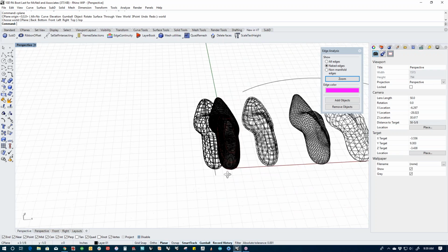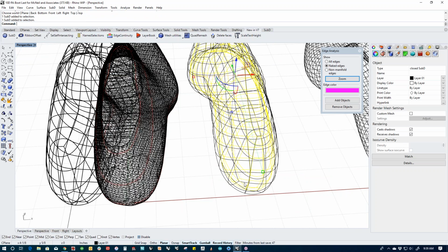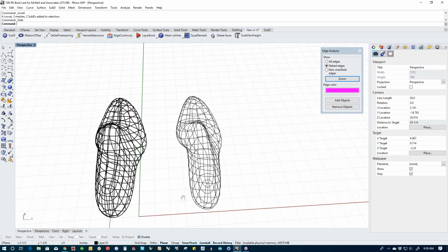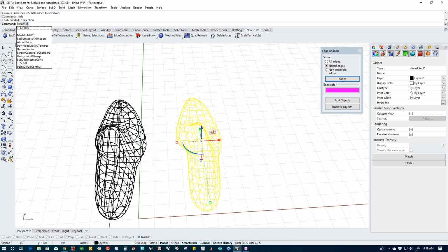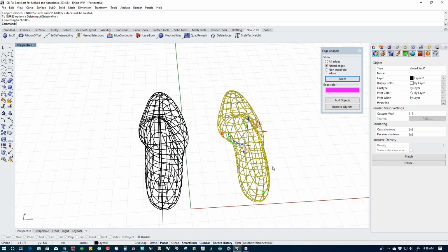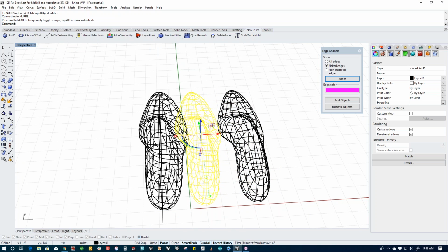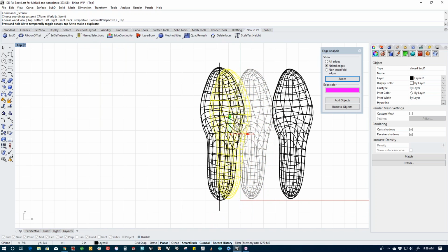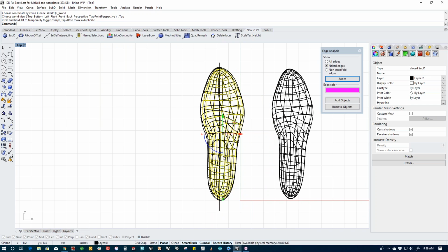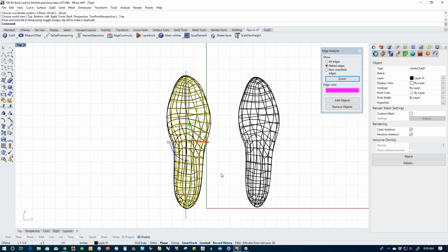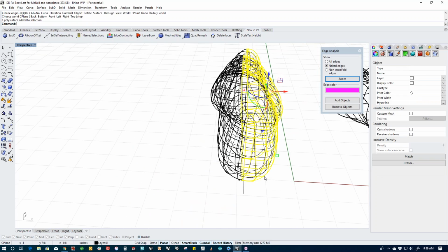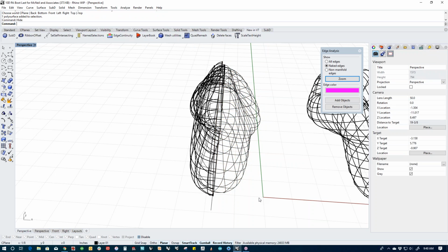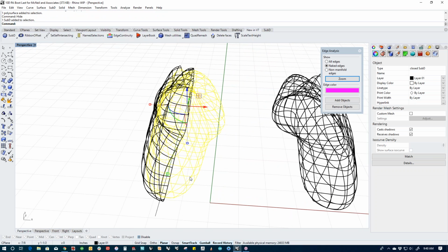All right, so we've offset this SubD, and we run NURBS on that, and then we line these two up. And I would have done this in one step. I wouldn't have done this in two steps. I would have done the outside SubD, then I would have offset, done the inside SubD, converted them both to NURBS, and then done this, but I just wanted to show this because it's a little bit more of a crowd pleaser. So, oops, that's the SubD.